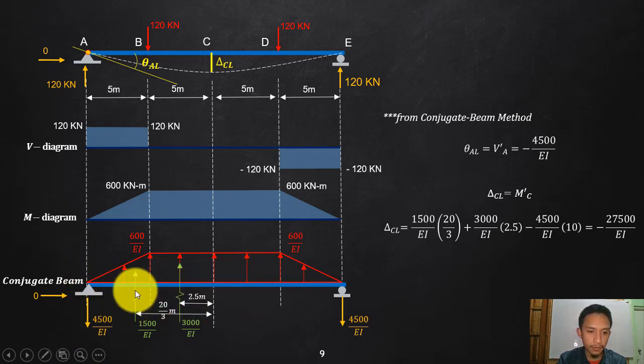So if you try to solve, let's say we do not know yet the support, all you need to do is take this one as load. Again, as I've said, that is a positive moment. In your introduction, a positive moment will be loaded as a positive load. What is a positive load? We assume that positive is going up. So this load, M over EI, will push your beam going up, so the reactions will be going down so that it will be stable.